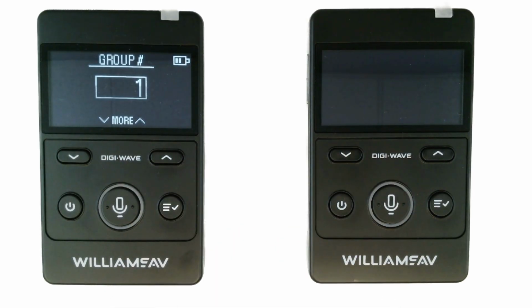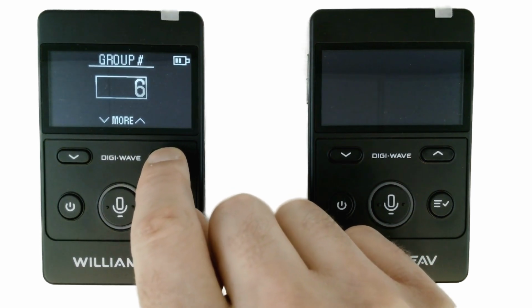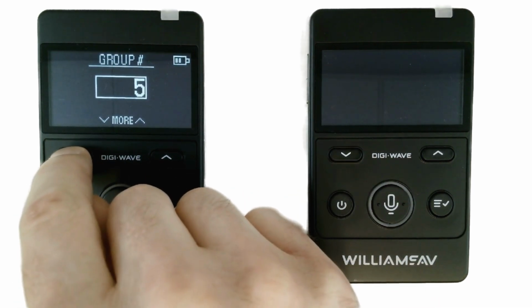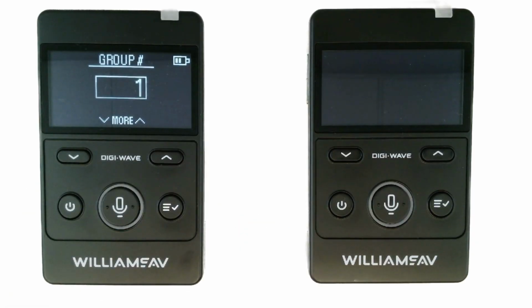Step 7. Group Number. Group numbers allow multiple communication groups to operate in the same space without interference, while maintaining privacy between groups where necessary. To join a group, all DLTs and DLRs must be set to the same group number. You can have an unlimited number of DLRs in a group and up to 1,024 DLTs. To keep it simple, we'll use Group 1 for this tutorial.